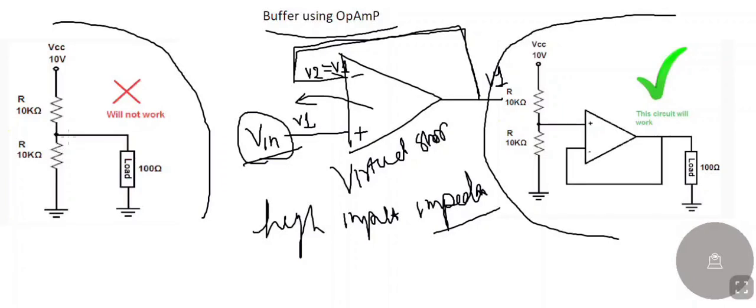Now let's understand, because if you try to see, in many cases we try to use this voltage divider, and we'll try to understand what is the disadvantage of using these circuits. Now what will happen, let's see, I have applied a 10 volt and there are two resistors and I want to calculate the voltage over these nodes. Okay, so first let's calculate the voltage over this node. Okay, this node voltage will be 5 volt because these resistors are the same, so this will be 5 volt.